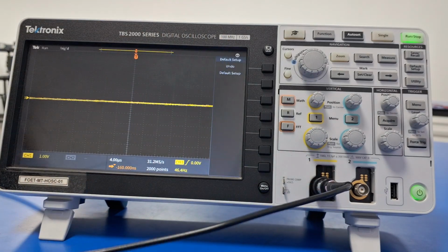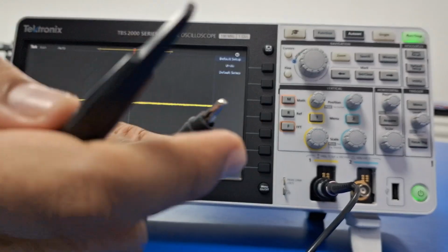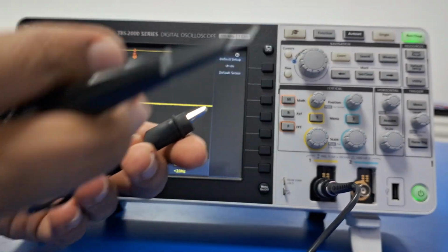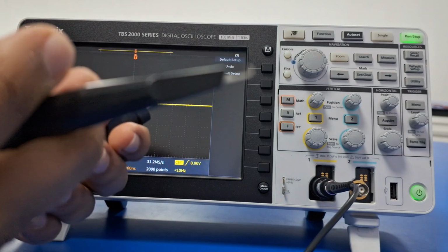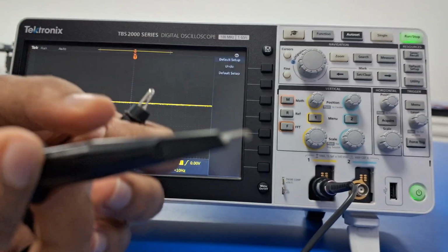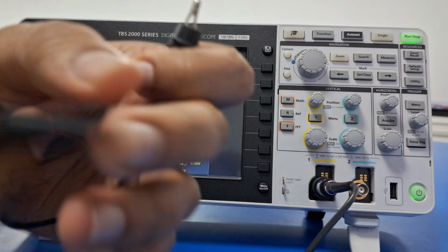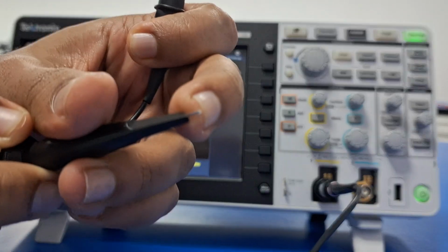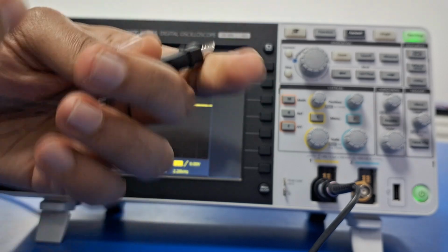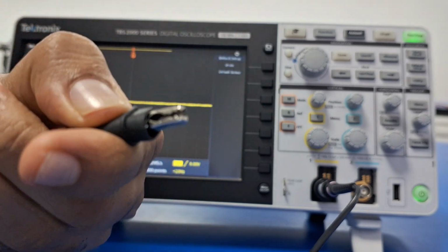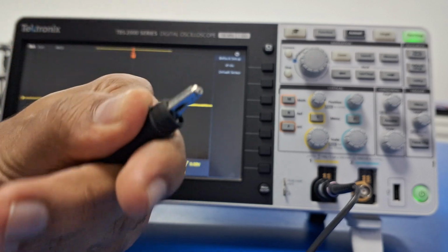On the other end you have these two. First, you have a probe, which you can retract using this lever, and you can attach this point to your test setup. Any pins, any components, you can attach it. And this crocodile connector is essentially your ground connector.